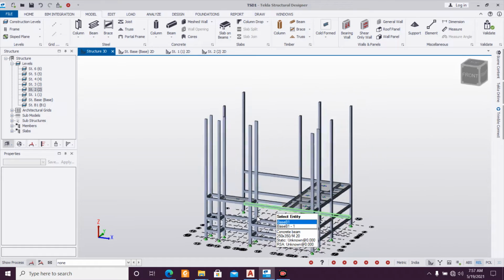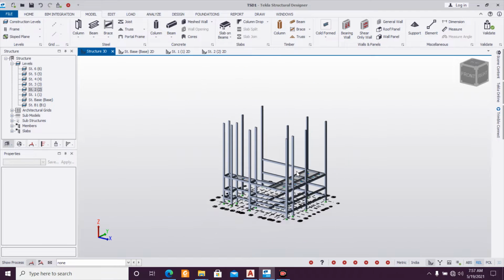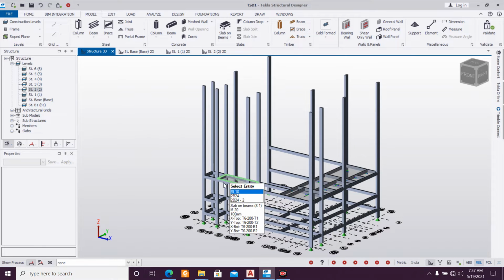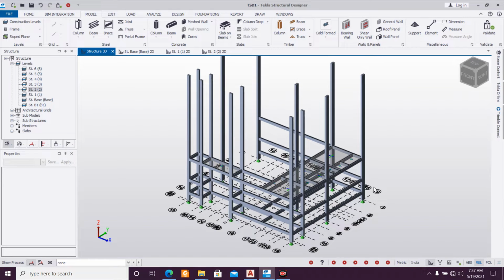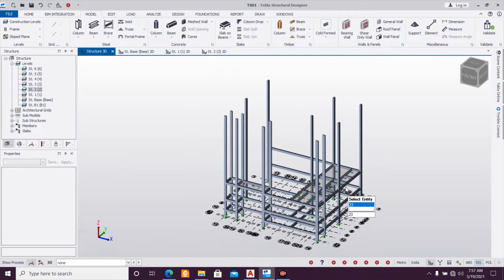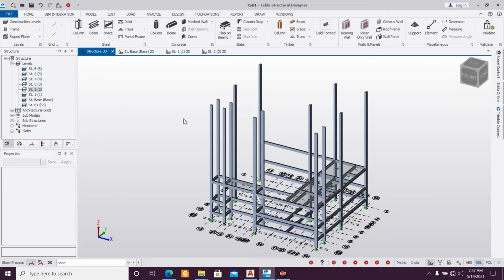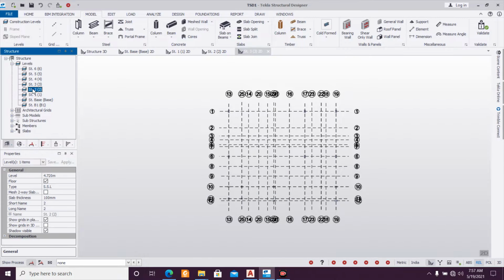Now we'll insert one more floor above it. I think this will be the same, because the slabs and all will be the same in this floor as well. We can give this beam in that portion as well. G plus 1. So basically, if the building height is 10 and 10 feet, 20 feet, we are also going here 6 feet plus 20 feet. So yeah, I think we can give this particular beam in the next portion as well. So let's just duplicate it first. We will be working in the structure 3 now.